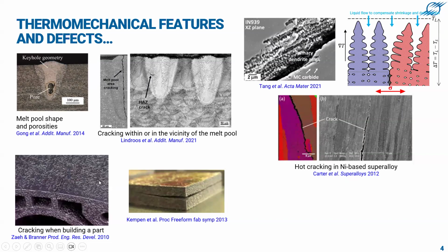It is very characteristic because the dendritic surface aspect can be seen along the crack surface. So you have also, I would say, more classical cracks that are simply due to thermomechanical effects, deformations, and combined stress, that may occur because of the cyclic temperature that is undergone by the material due to the successive layer deposition. Examples are given here. So we can realize that the scale at which those phenomena will be studied can be very different.